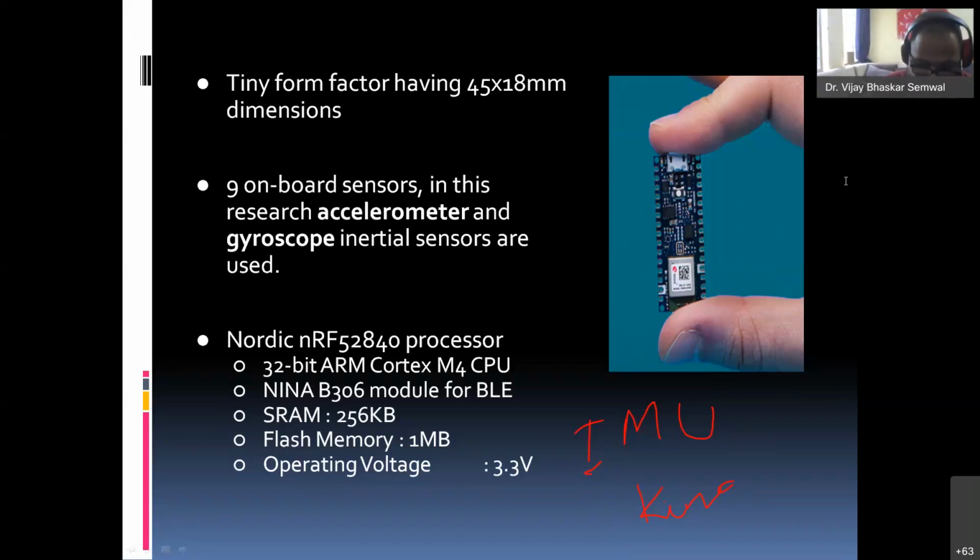Any more questions? I think this is clear. The IMU sensor, inertial measurement unit sensor, comes as a 9-degree IMU sensor. You will get this for 1,000 rupees. 1,000 is also high. An accelerometer you get for hardly 200, 300 rupees, and accelerometer and gyroscope together are helpful. So better you purchase a 6-degree IMU sensor, by which you can capture the data, wear it, and track the activities.